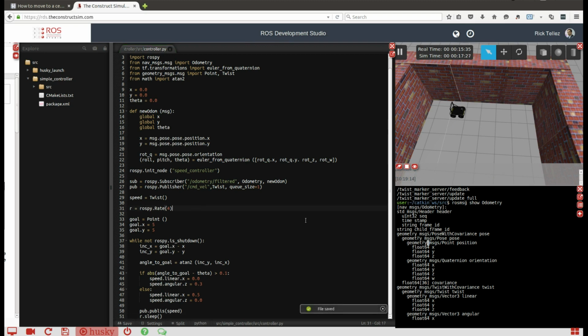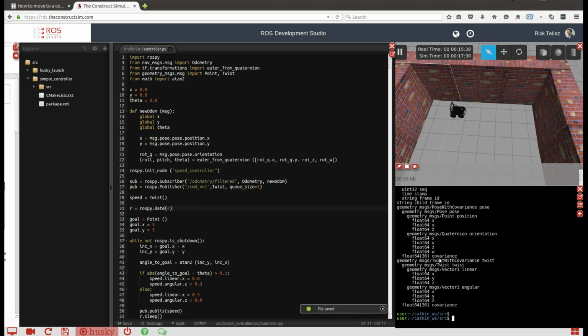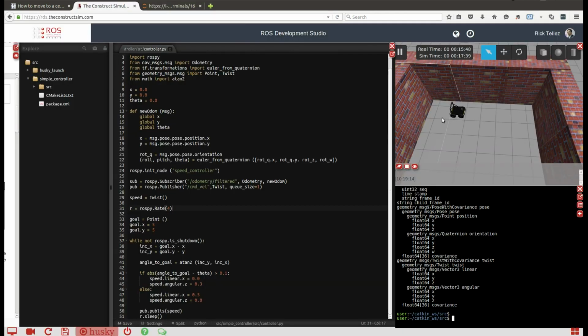And in order to see how it looks, let me open RViz so we can get a clearer vision of how it is moving in the odometry frame, because here we cannot see the odometry frame and we don't see if it is moving in the correct direction based on the odometry axis. Okay, for that I have opened a new shell here, and I'm going to launch RViz.